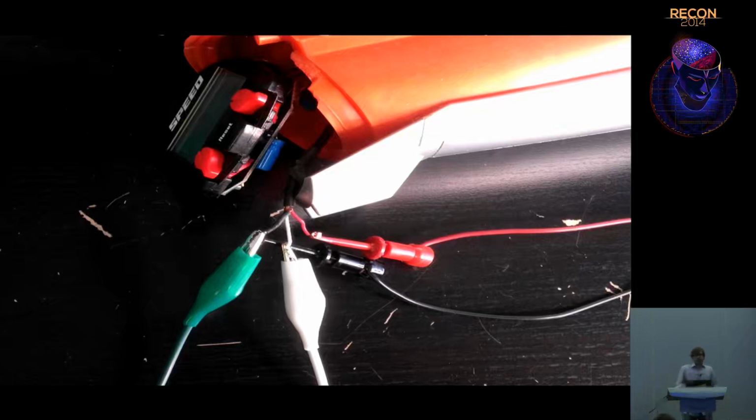It has a battery pack, it has this radar section, and then it has this separate board that you can see there with the little speed control and stuff, or the LCD on it. The little LCD control panel is a completely separate unit from the radar unit inside here. So I buy these things on eBay, and oftentimes they show up at my house broken. But usually the part that's broken is the controller. And if you just hack that off of the radar section, you can tap into those 3 wires at the bottom there. All you have to do is supply power to the radar section and then pick up the return off of it. Easy. And I plug in 2 of those wires to my HackRF.